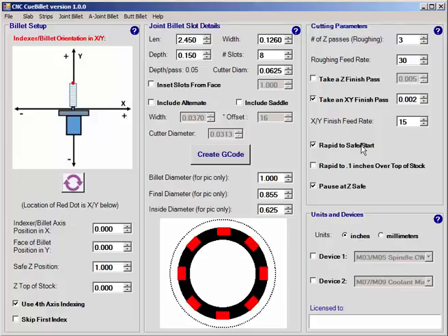The bottom right panel includes the ability to change from inches to millimeters and the option of turning devices on and off via machine commands in the G-code program. When the pause at Z-safe is checked, devices are not powered on until after the user continues the program.